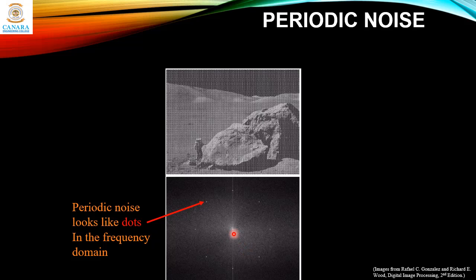The origin is basically zero frequency. As you move away, you get low frequencies, and move further away, you get high frequency components, right? So in any direction you move from the origin, you get higher and higher frequencies. So you can zero in on one particular frequency here. Okay, for this ring, you can identify what frequency it is, and you can just suppress this particular frequency to get rid of the noise here.